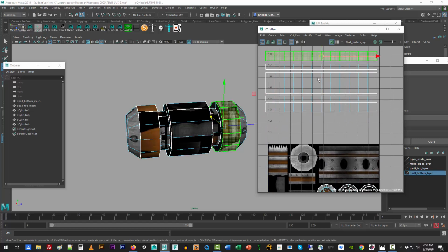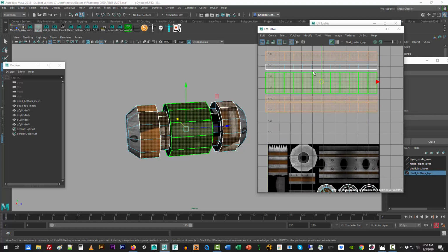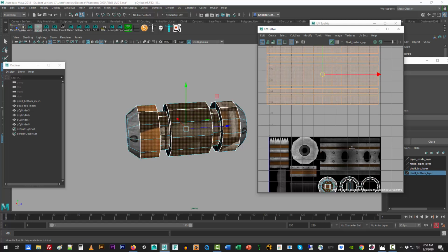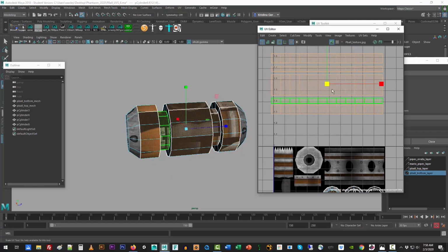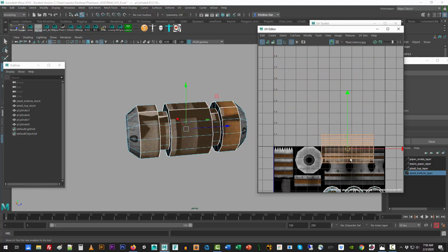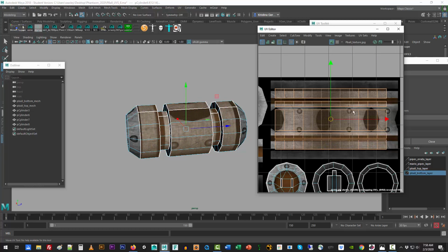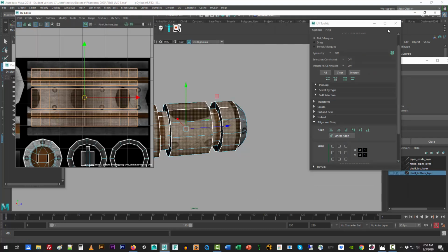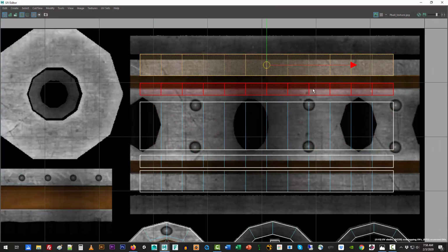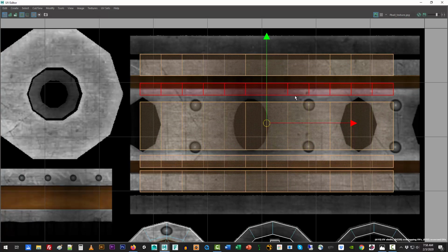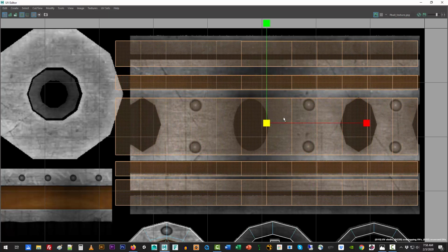First of all, we don't want to scale each of these individually, because what we've done is we've made the texture consistent right here in this section where you see these sort of darker holes. That's for this entire doorknob lightsaber model that we've made. So let's drag things down first, press F, and without looking at the 3D modeler, let's just go into the UV window, pull back just a bit, and start arranging these out so that at least first we can uniformly fit the scaling of what we need. And that looks about right.